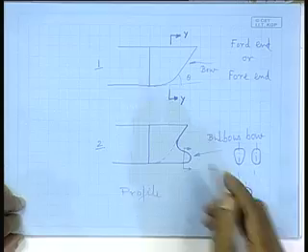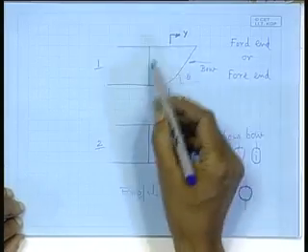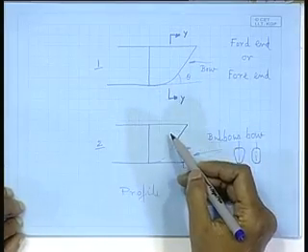Now, once the lines and how the hull form would be has been decided, then one goes for the scantling calculations, followed by stiffening arrangement, which is the aspect we are looking into. As we go for stiffening arrangement, we see that a little extra care is given to these forward end constructions.